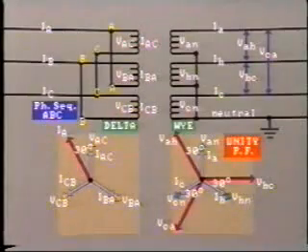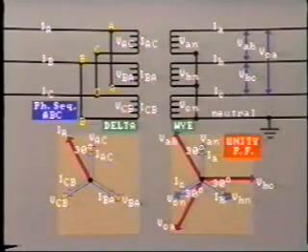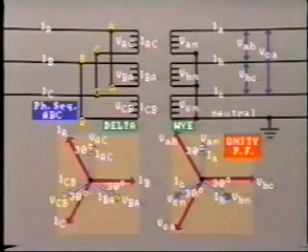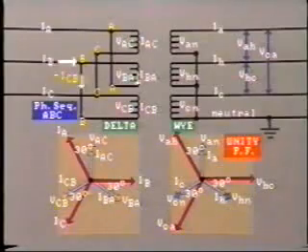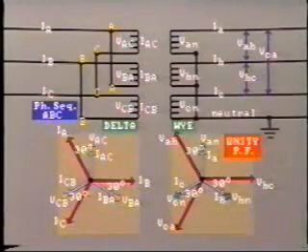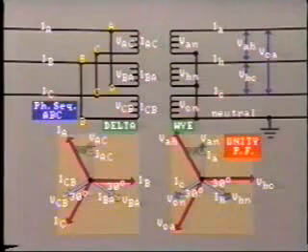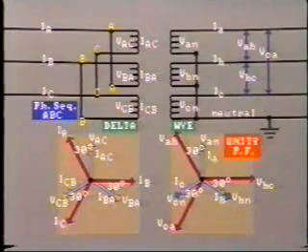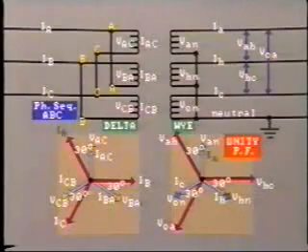We find by inspection that the line current IA will be 30 degrees ahead of its respective phase voltage VAC. Similarly with line currents IB and IC. IB equals IBA minus ICB, and IC equals ICB minus IAC. So there is a 30-degree phase shift of currents as well as voltage in a delta Y transformer, as you would expect. The line current IA in the Y-connected secondary is 30 degrees lagging the line current IA in the delta-connected primary side.